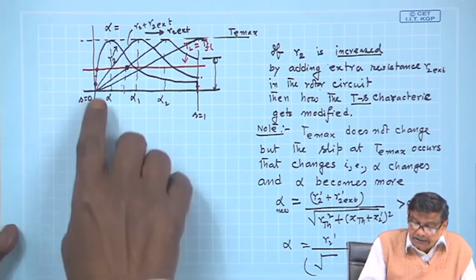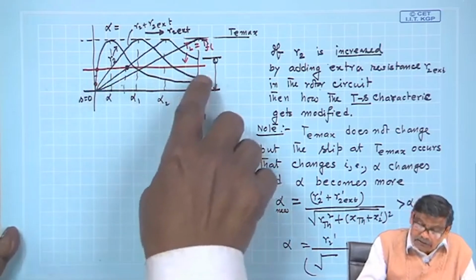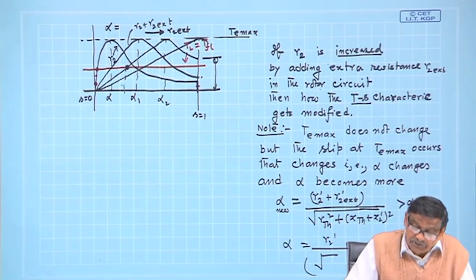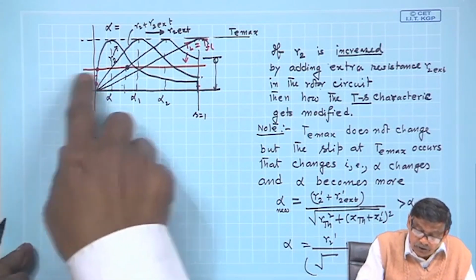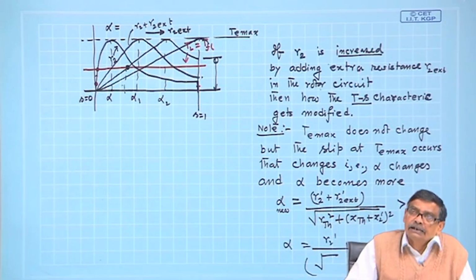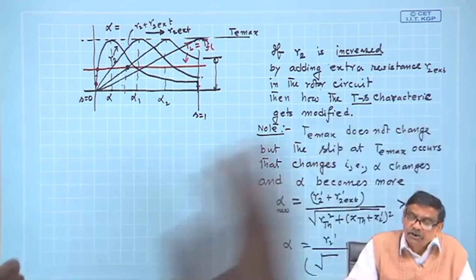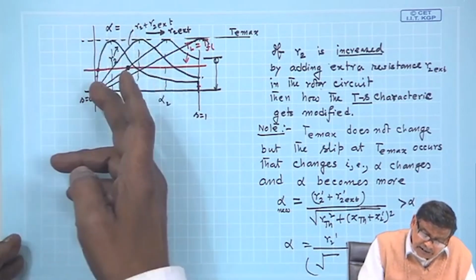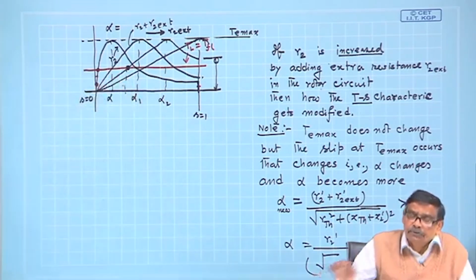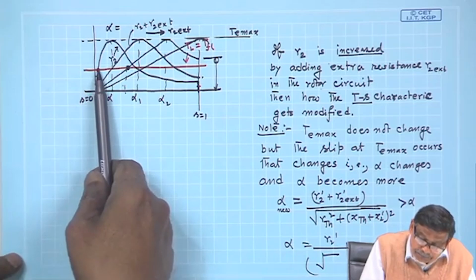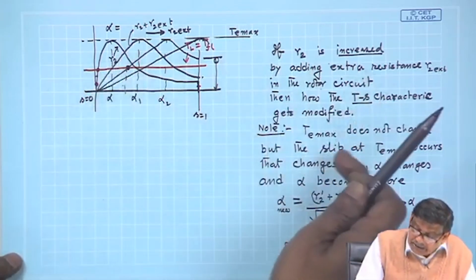Therefore, not only that, there is this problem that with inherent rotor resistance, although the machine is capable of starting against full load torque, one way out is to not connect that full load opposing torque at the beginning. Do not do anything with the rotor, keep it shorted right at its terminals, and then after the machine settles down to no load speed, put that opposing load torque on the shaft, and then the machine will operate here. But I am now telling another interesting thing.